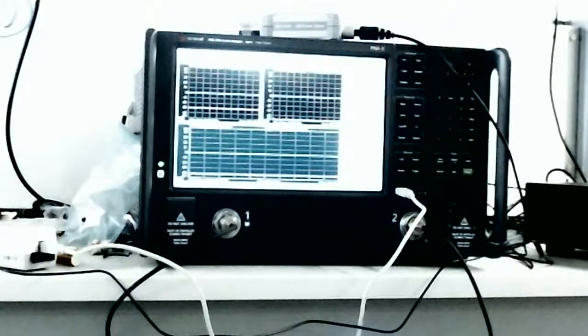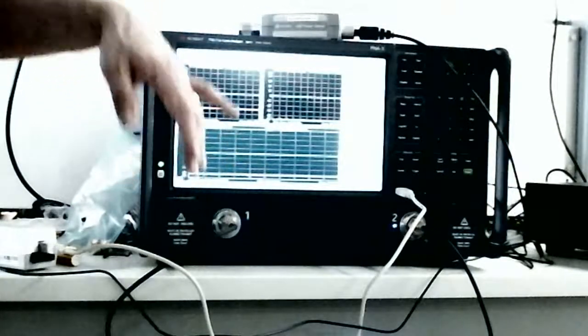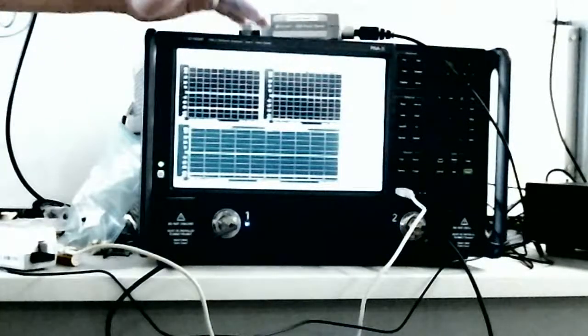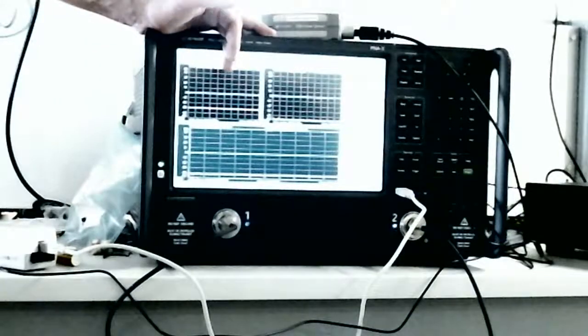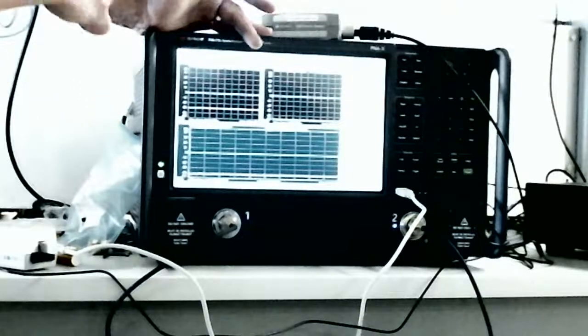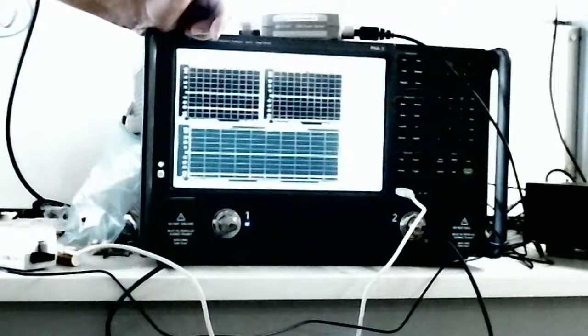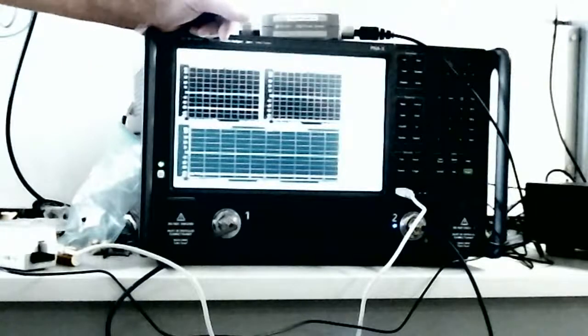This is a vector signal generator. You could use this as even an analog, put it in here and use an external combiner, and there's an intermodulation app, so you could do swept IMD, and it would control that signal generator as if it were part of this instrument. It would sweep either the tone power or the tone spacing or the tone center frequency and keep the tone spacing and tone power the same. And it would do all of that for you for amplifier characterization.